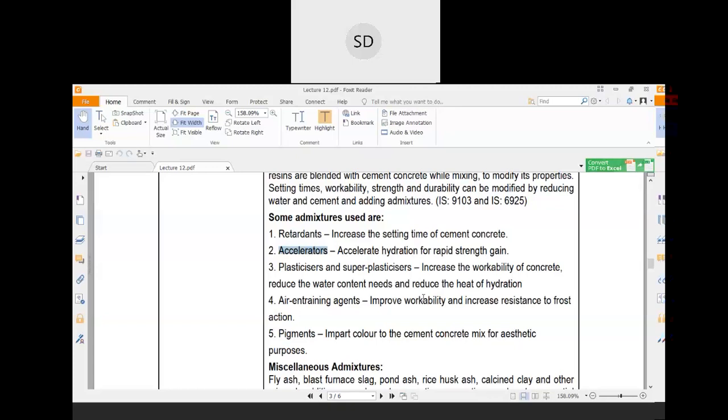It is needed that the cementitious material you have put over the broken portion hardens rapidly so that it can be used as soon as possible. Otherwise, the traffic would be hampered. In such a case, you need accelerators to increase the rate of hydration so that the cementitious material hardens very fast.